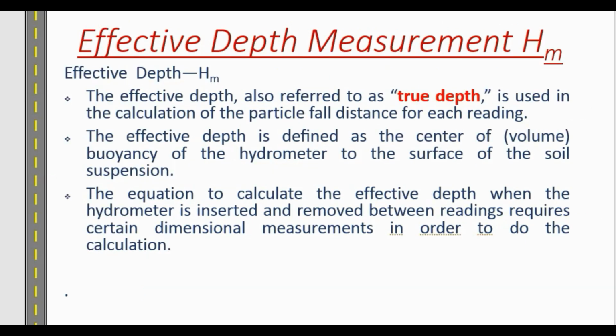Then effective depth, that is a crucial part of the calculation. The effective depth, also referred to as true depth, is used in the calculation of the particles' fall distance for each reading that we take in the sedimentation cylinder after mixing the soil and dispersing agent.